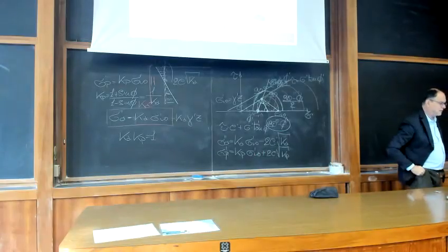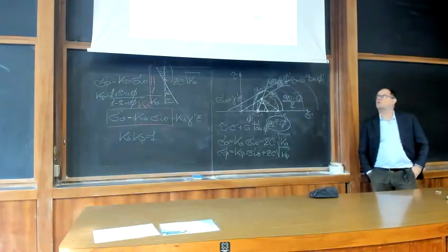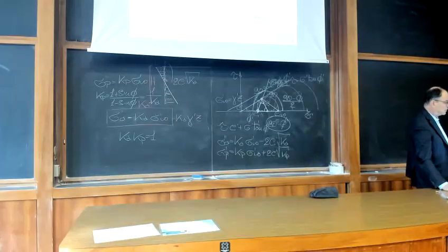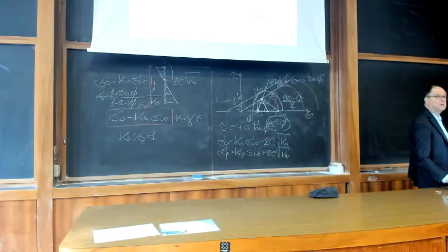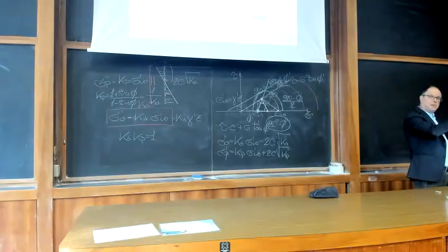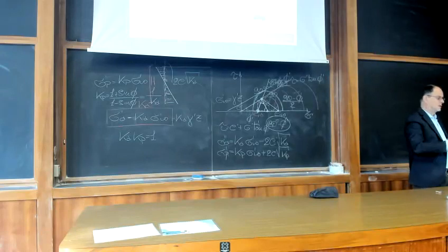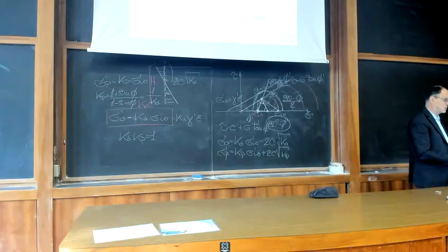Now, there are several shallow foundation types. I'm sure you are familiar with the single foundation that you see, which can be a square foundation, which is just an enlargement of your column. As I said, this is a plan view. You have the column and you have to enlarge it in order to decrease the stresses transmitted to the soil.